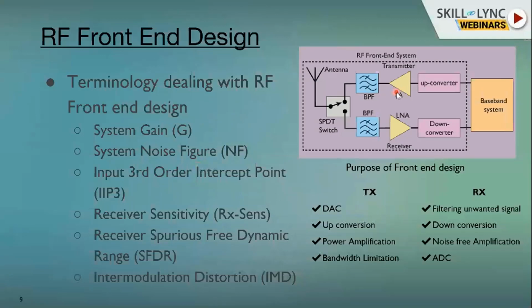As I mentioned, when we go for multiple frequencies over a bandwidth, this particular power amplifier or low noise amplifier behaves very weirdly because of the restrictions over the design. So this is one of the challenging parts while designing or choosing the components for the system design. Similarly, for the receiver, the spurious free dynamic range is basically the bandwidth which we are covering, and how the behavior is there. These are the numbers that have to be known before we design the RF system.